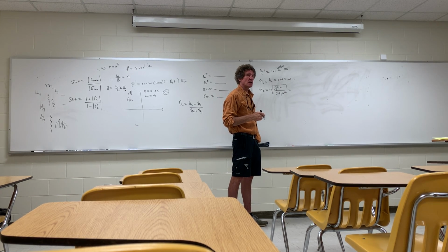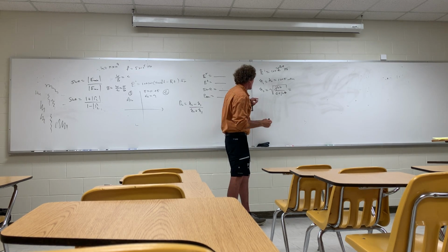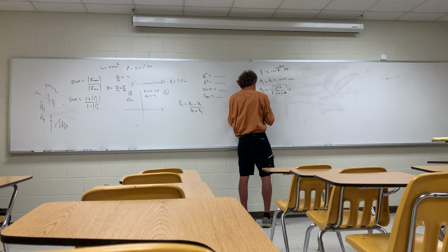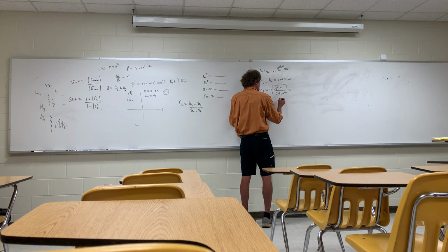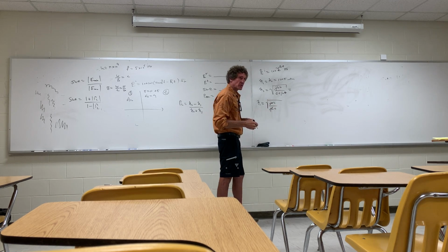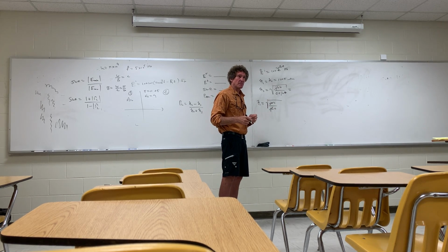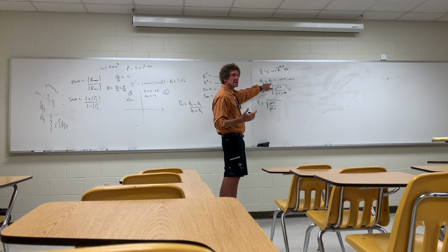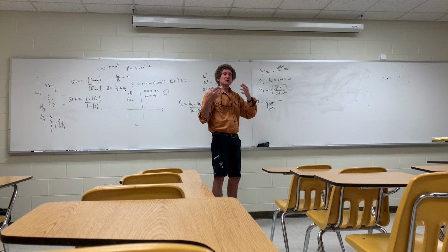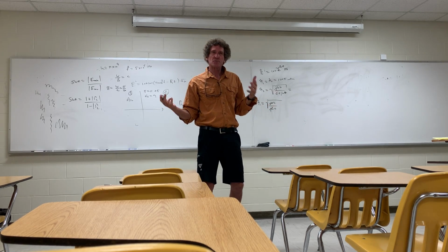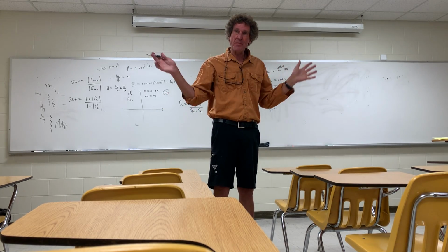Can you describe the relationship between eta naught and eta 1? Well, eta 1 I got from air, right? So the square root is j omega mu, but since sigma is 0 for air, it's over j omega epsilon. The j omegas cancel, you get the square root of mu over epsilon, that's 120 pi. Eta naught is considered 120 pi, it's in air. It's the intrinsic impedance of free space.